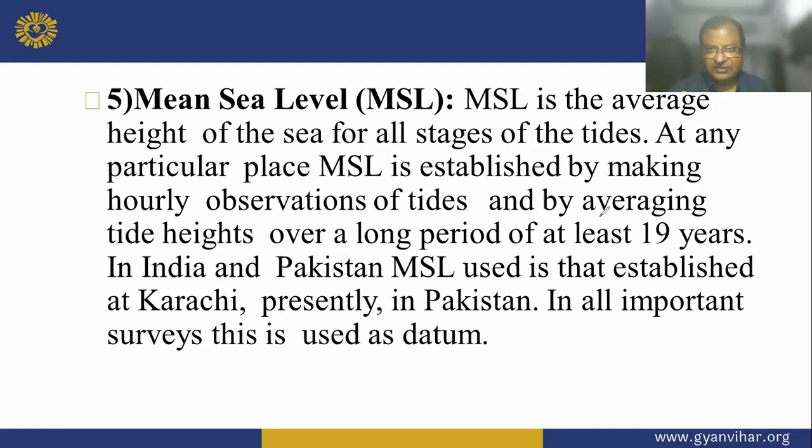MSL is established by making hourly observations of tide and averaging the height over a long period, at least 19 years.